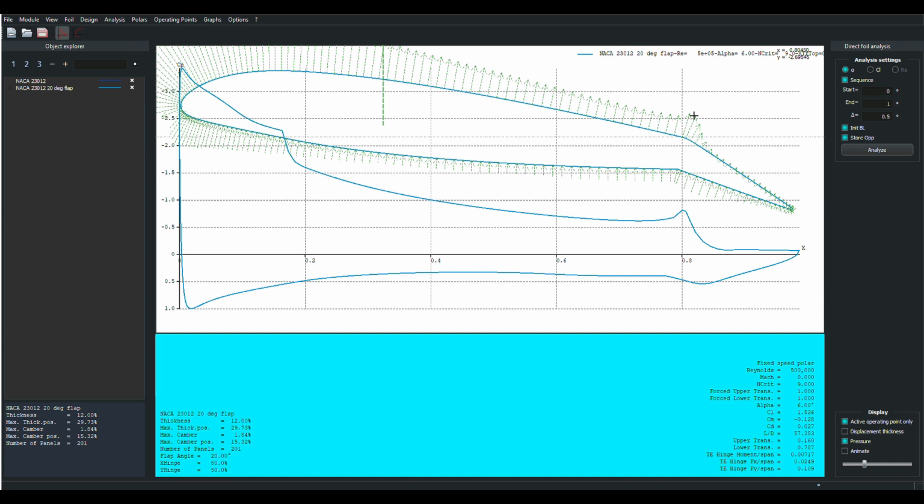But as Peter and I talked through this, he gave me the wonderful layman's explanation, in addition to this explanation, that would be easy for lay people to understand. The flow's coming along here on the surface, and it has very little energy in it, and then you ask it to turn a corner. It's got to turn this corner and follow this surface. And turning corners takes energy, and there's not much energy in there. So it's kind of a double whammy.